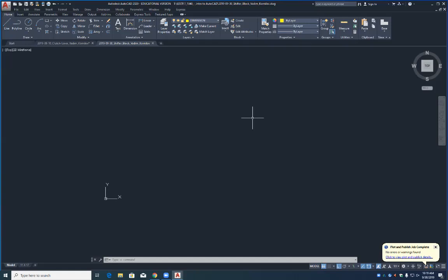When we create a section line, though, everything is twice the size. Everything. So, how long should our dash be here? 1/4. What about our gap? That makes sense? We're just doubling the size. For the size of the sheet of paper or for this specific hidden line?